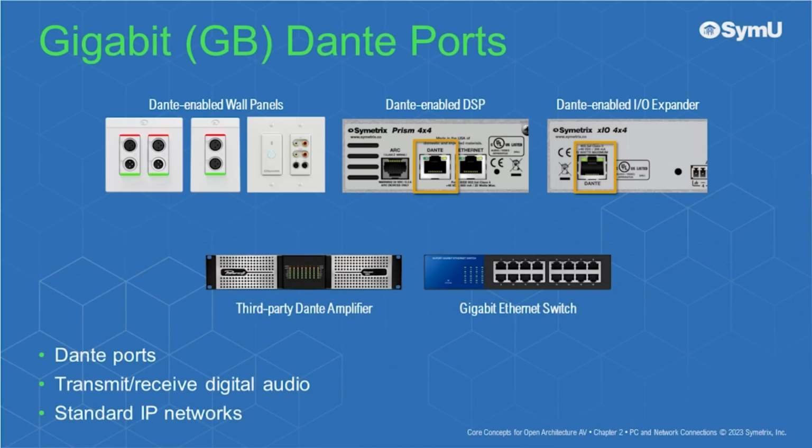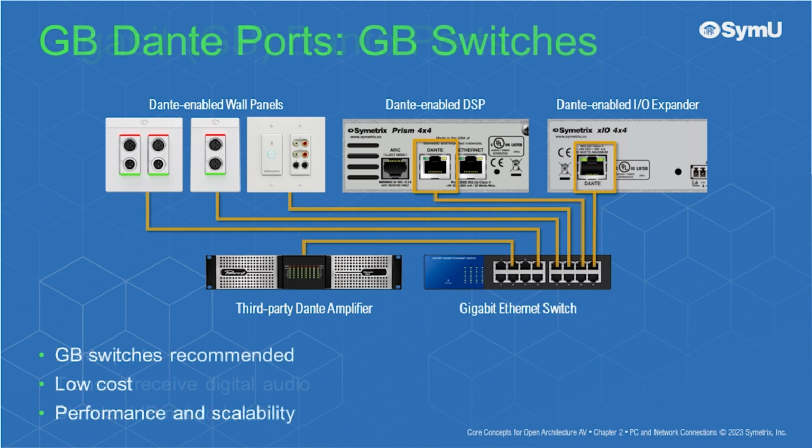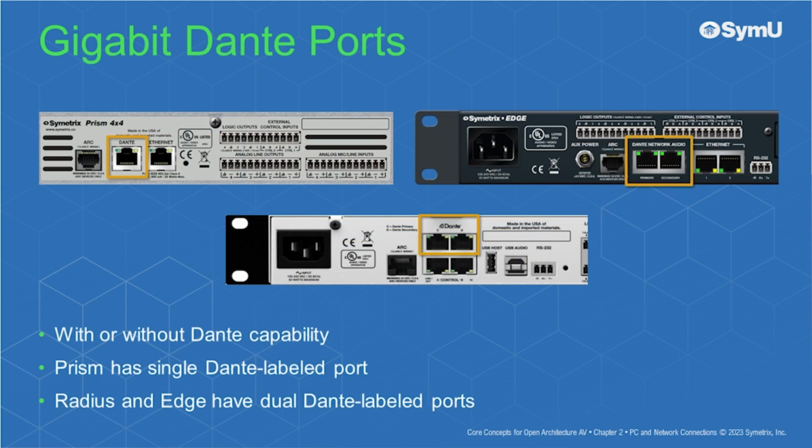Dante ports transmit and receive digital audio across standard IP networks. Gigabit switches are recommended for Dante networks due to their low cost and clear advantages in performance and scalability. Composer Series DSPs can be ordered with or without Dante capability.